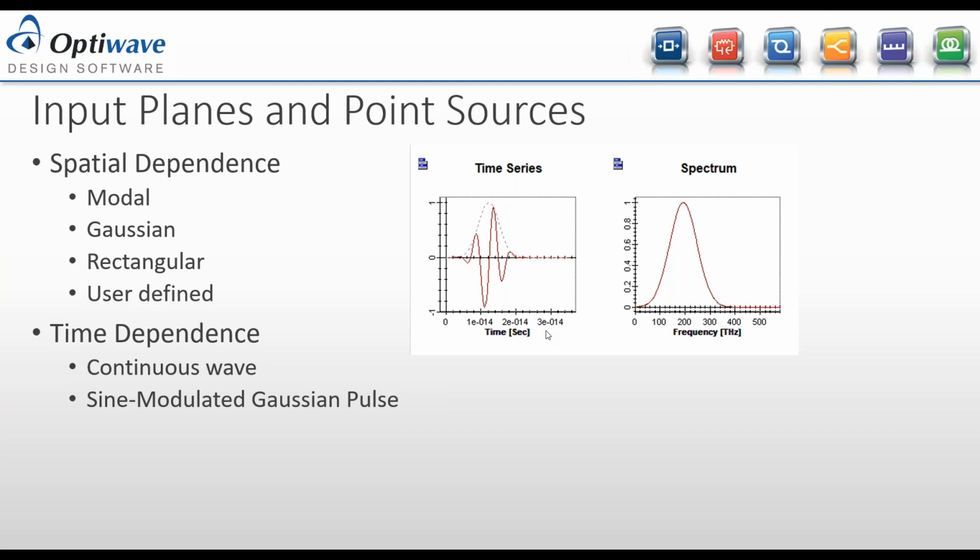This is useful also because it allows the OptiFDTD tool to automatically finalize the simulation, because there'll be some transitional period from when you're ramping up the source to the sinusoid. There's a beginning period, and also it takes time for the field to propagate to all corners of the simulation domain. But after everything is going, it should reach some type of steady state, right? So then the simulation software can figure this out and then stop the simulation once this condition has been reached.